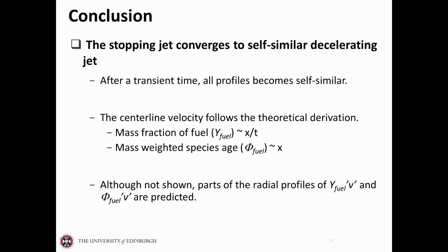That's a very technical question. What's your outflow boundary condition for? So we have a wall at the inlet, and then the sides are a Navier-Stokes boundary condition. So there is actual entrainment coming into the jet. And for the outlet? Just a Navier-Stokes outlet.